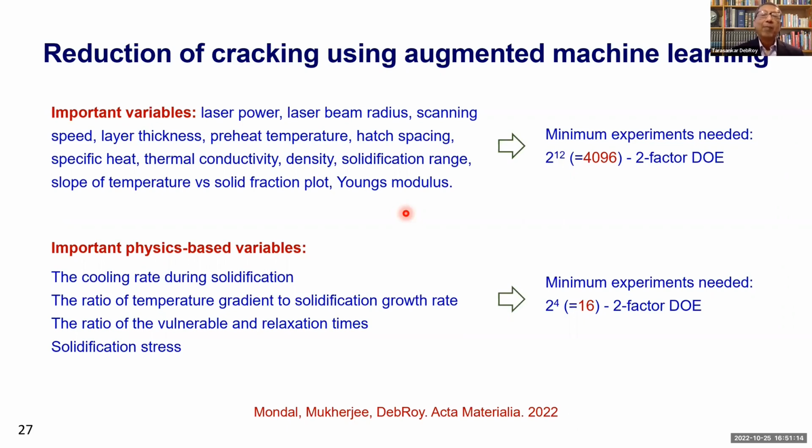If the Reynolds number is higher than 2,100, the structure of the flow is going to be turbulent. If the Reynolds number is 5, it's going to be laminar flow. So it is like this here. If you know physics, you can mix physics with data-based models.